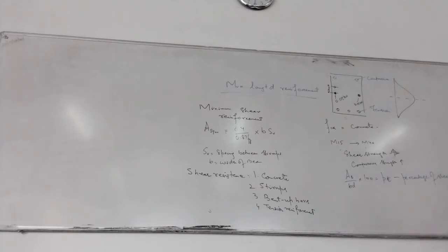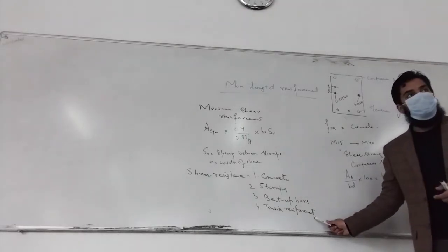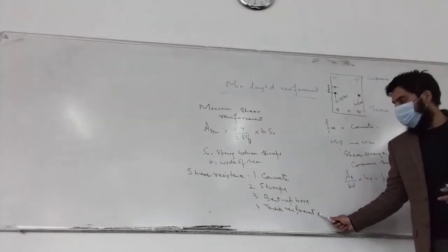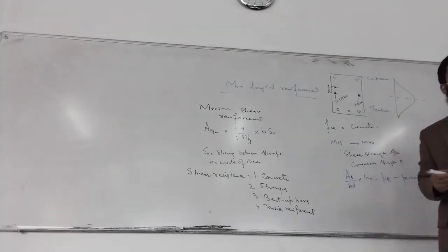Now this is the percentage variation of the longitudinal tension steel. Along with that, if you look from top to bottom in the M15 column, what is happening is 0.2 to 0.71. So it is also increasing with the increase in the percentage of tension steel. What does that mean? Shear resistance is also dependent on the tension reinforcement. So from this table we learned both things.